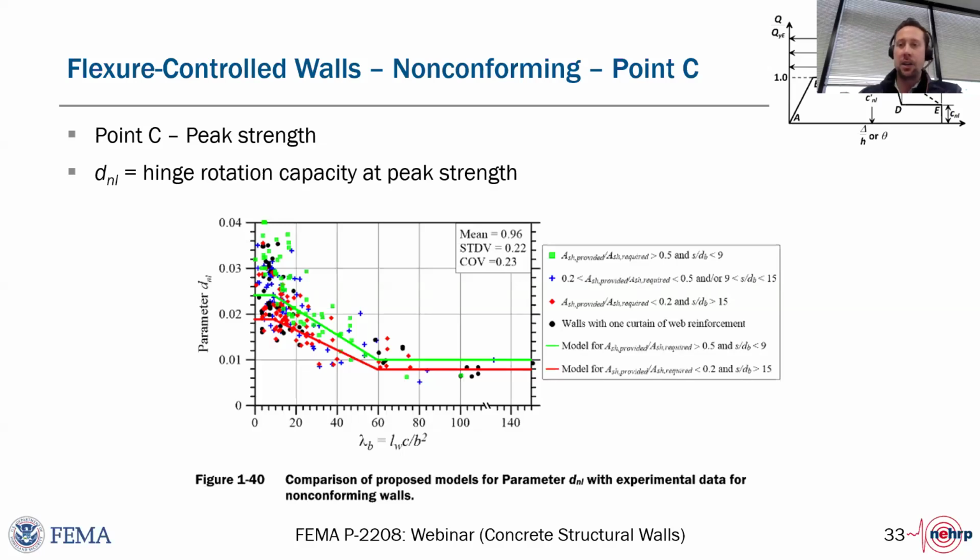That's up here on the curve. That would generally be higher than your yield because you have strain hardening, but it's not just the steel strain hardening that affects things, it's actually concrete overstrength also. This is a nuance that is probably lost if you don't read through these technical recommendations in depth. It's worth mentioning because we basically allow one factor, 1.15, to understand the difference between your ultimate peak strength and your yield strength.